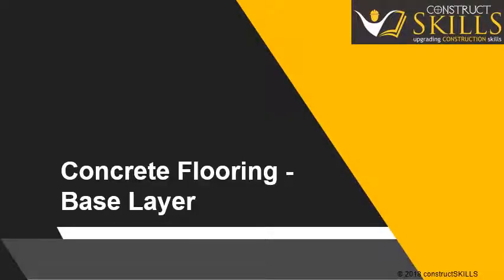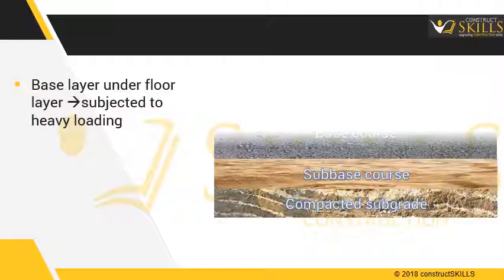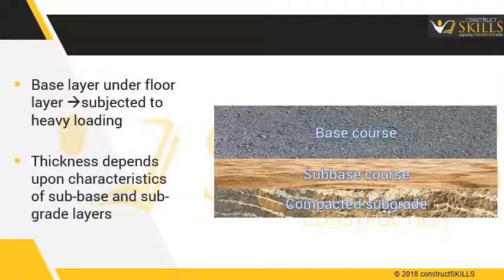In this guide, we are going to learn about base layers. We will now be discussing the base layer. The base layer is immediately under the surface layer, and so is subjected to heavy loading. The thickness of the base layer depends upon the characteristics of the underlying sub-base and subgrade layers.